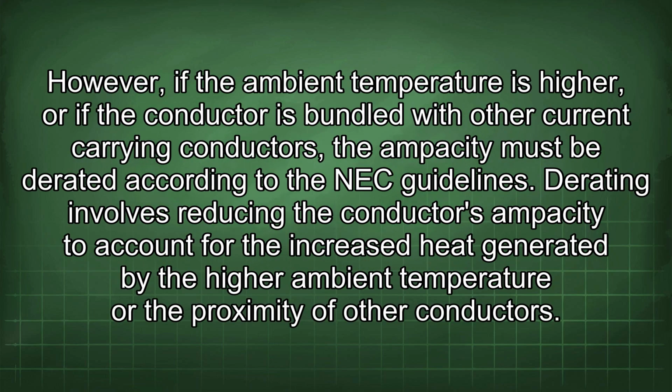However, if the ambient temperature is higher, or if the conductor is bundled with other current-carrying conductors, the ampacity must be derated according to the NEC guidelines. Derating involves reducing the conductor's ampacity to account for the increased heat generated by the higher ambient temperature or the proximity of other conductors.